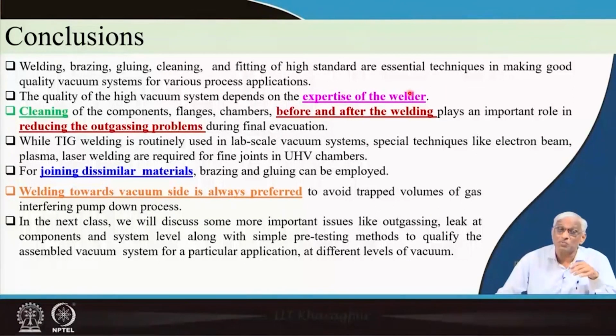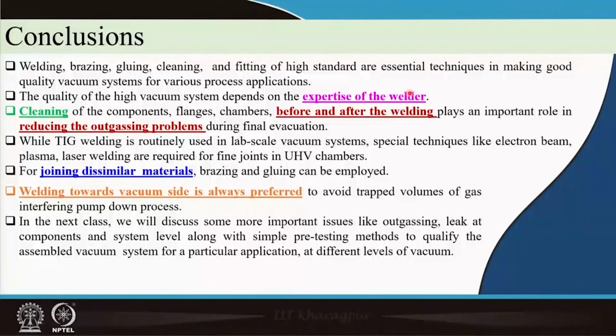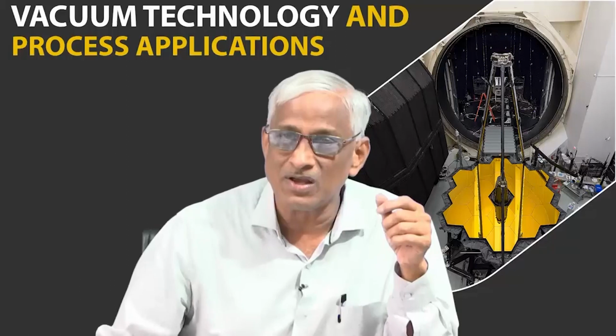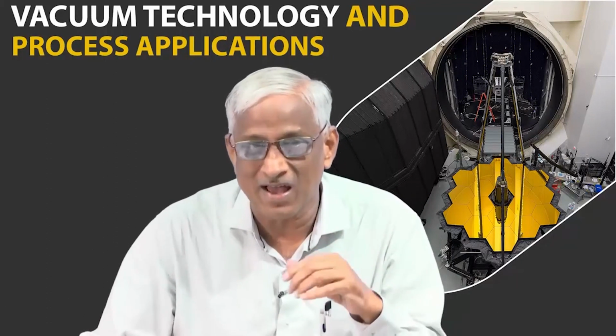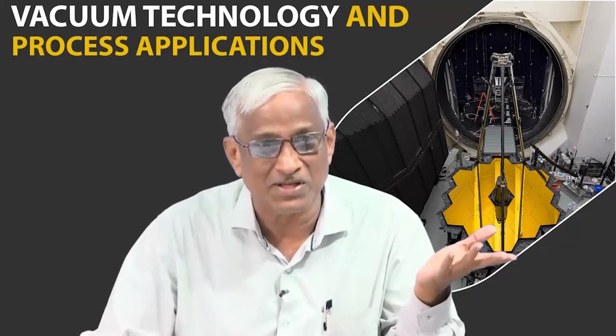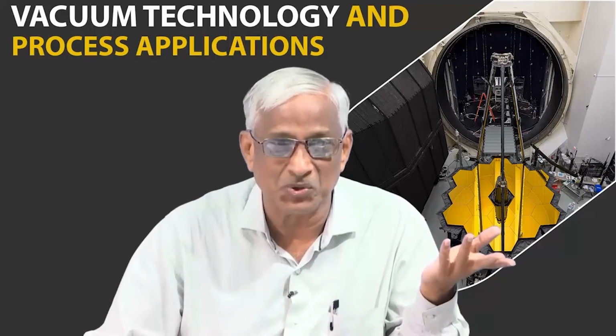The chamber should be compatible more with the process chemicals rather than with cleaning issues or ultra fine leaks. We did not care there, but we have to care here, because micrograms matter. Here, milligrams in the high vacuum, grams in the poor vacuum. For the same allowable pressure rise, micrograms are good enough to spoil the show.